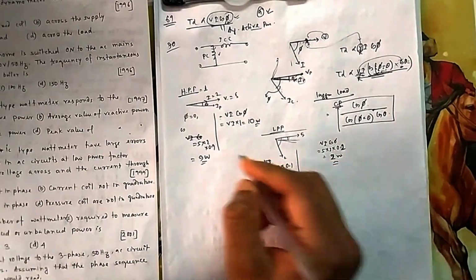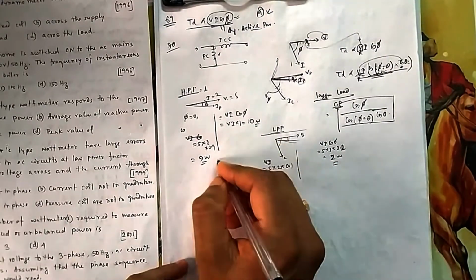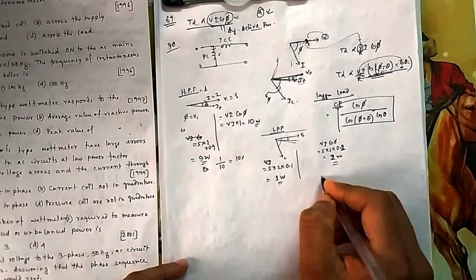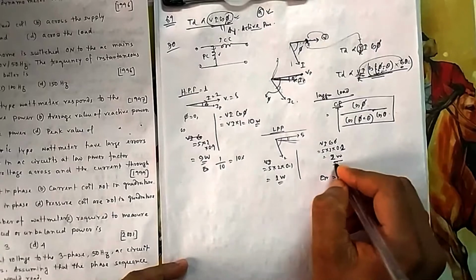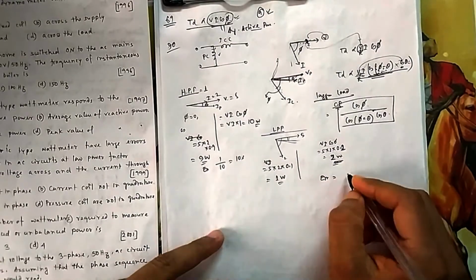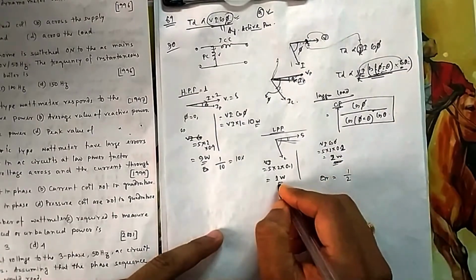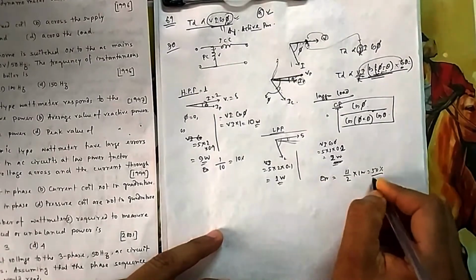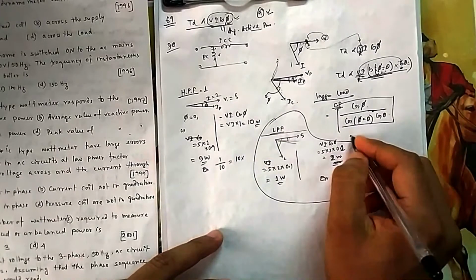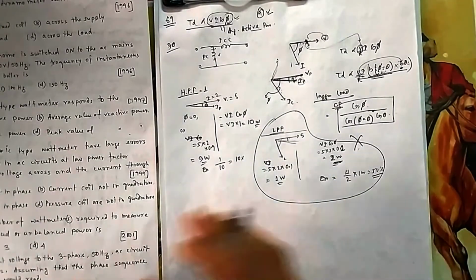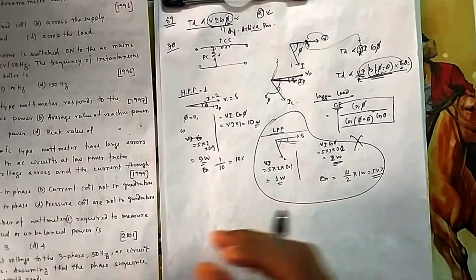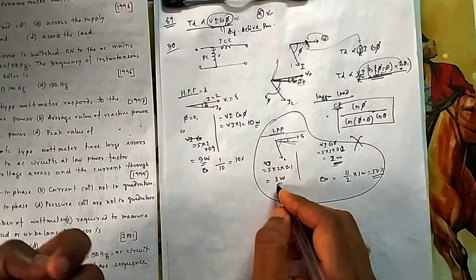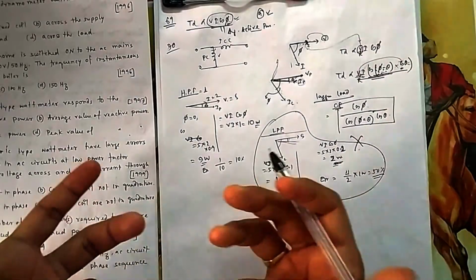Now you see the error percentage. Here it is an error of 1 watt out of 10 watt, so what is the error percentage here? 10%. What is your error percentage here? Actually it is 2 watt, but you are getting 1 watt. So the error is 1 out of 2, that is 50% error. So it is not feasible. 50% error, how can you accept this? So it is a huge error. The error percentage goes very high because your measurement is so low. Even a small error will give you a large percentage because you are measuring a low value.